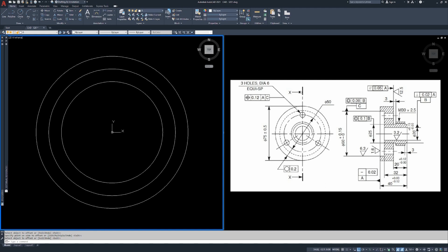Now what we want to do, because we have a crosshair in here, these are centerline line types, implying the center line of this circle. So what we want to do is just throw a polyline in there, PL, from the center point. We're going to just pull it straight up. And then we're going to window select it, grab that center grip, pull it straight down.